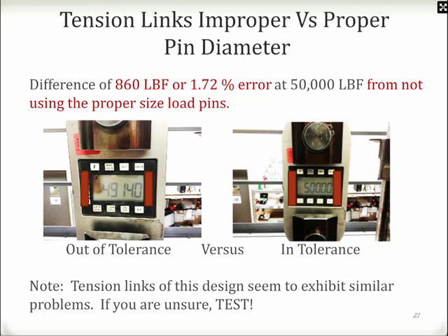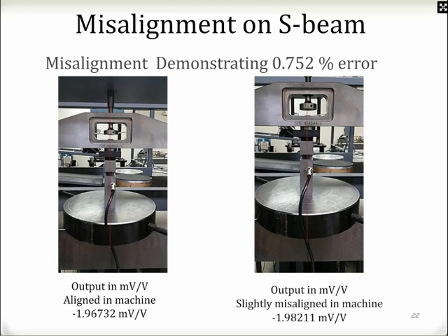I must preface this: tension links of this design seem to exhibit similar problems. If you are unsure about this, you can easily check it. You can test it. We can fabricate adapters. We have a full machine shop. We can fabricate the proper tension members and adapters. You can call the manufacturer. Typically, they don't publish this stuff online, but in almost all cases they have worked with us and given us sheets on what the proper pin sizes are for these types of instruments. Again, most of them exhibit this error. If you're unsure, test it.